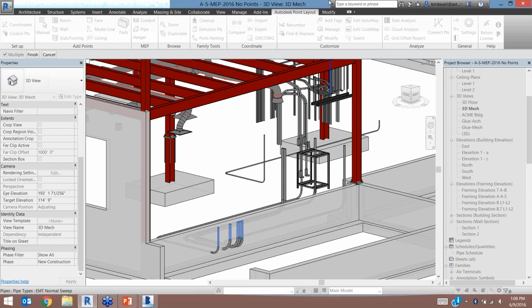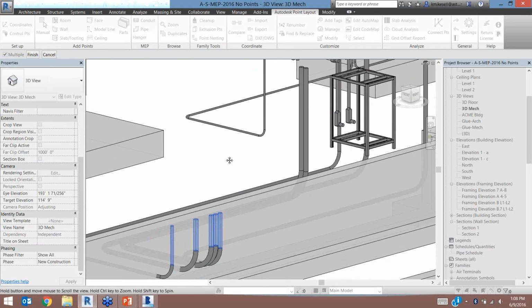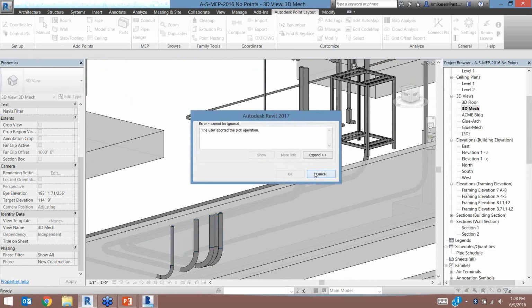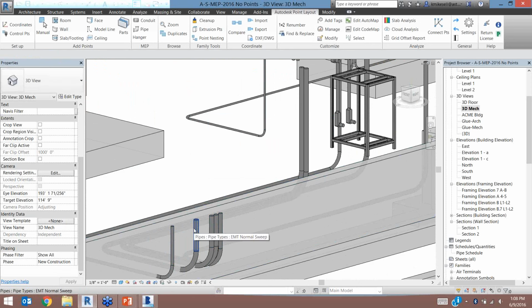It depends on how you do it. So if you add the colors the way I was showing you with the modify, they are view sensitive. If you add the colors to the point families themselves, they will be visible on any of the views that you have open.